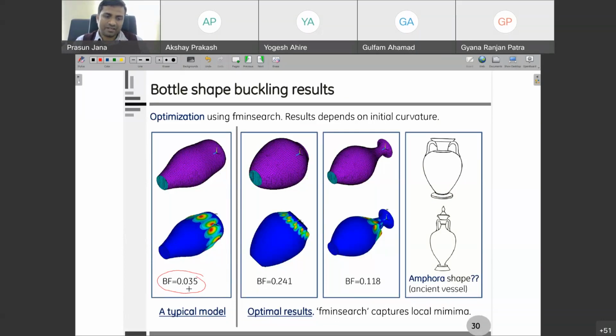When the buckling factor is less than 1, that means in your analysis setup you are actually giving a very high load. It is a linear relation for eigenvalue buckling analysis. If you increase the applied load, then the buckling factor will reduce, and if you reduce the applied load, then it will increase, because the multiplication of these two gives you the ultimate buckling load.